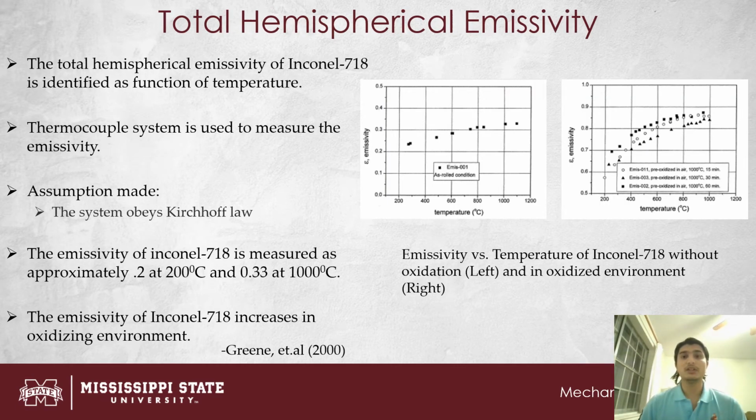Total hemispherical emissivity. The total hemispherical emissivity of Inconel 718 is identified as a function of temperature. The research done by Green et al. found that the emissivity of Inconel is 0.2 at 200 degrees centigrade and 0.33 at 1000 degrees centigrade. This shows that the emissivity is a function of temperature.